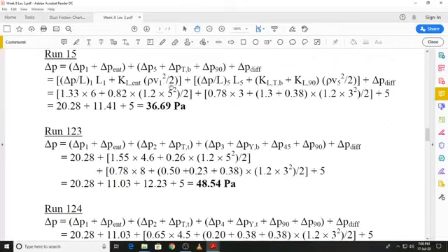You will use the velocity v5 when we calculate the dynamic losses in segment 5, and that will be all because we only have 2 segments. So when you move into a fitting and want to calculate the dynamic loss, you will calculate it based on the velocity in the downstream segment. So you won't use v1 over here, you will use v5 to calculate the dynamic loss.